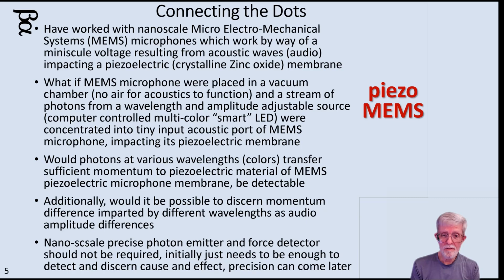There's a nanoscale piece of zinc oxide inside this chip, and the acoustic waves, like air hitting this little tiny chip, produce a voltage due to the piezoelectric effect. That's where you essentially exert force upon crystals, and the crystals produce electrons, and the electrons are voltage. So that's a MEMS microphone, a micro electromechanical microphone. And these are relevant in everything that you do today that has a microphone in it.